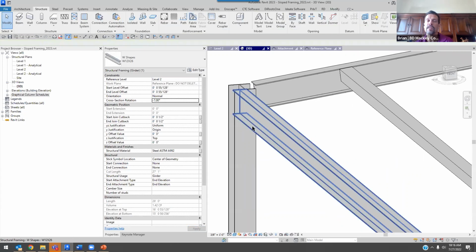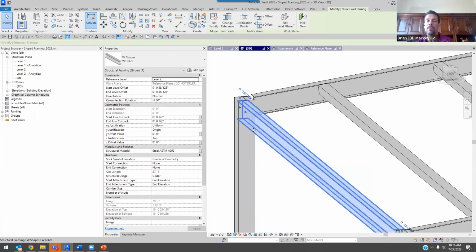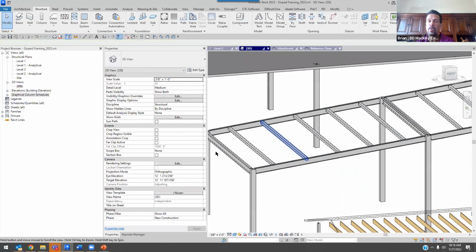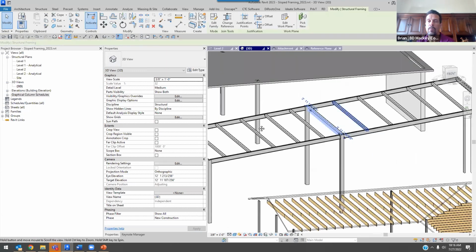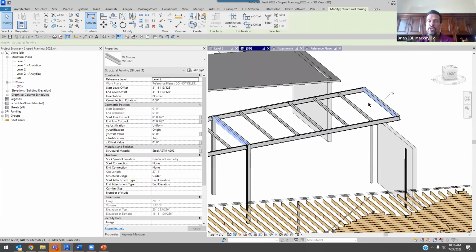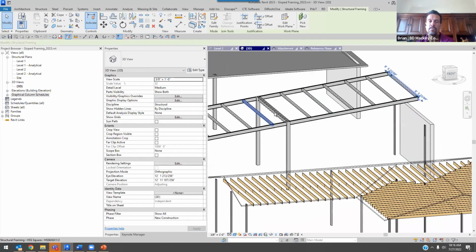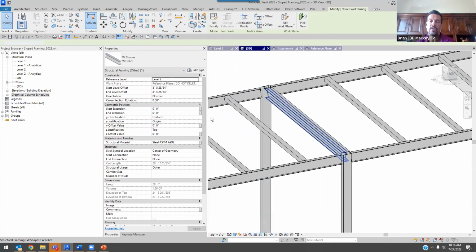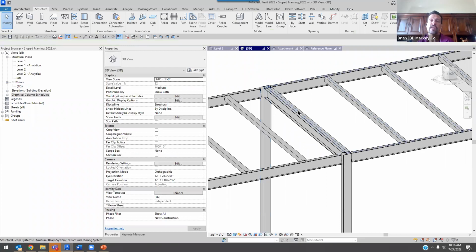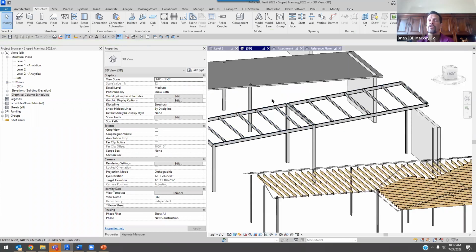So when we start setting that up, if you did want your beams plumb, you're going to have to come through and determine, oh, well, I needed that one plumb, maybe I needed that one plumb and that one plumb. So I should be grabbing, not what I meant to do, this one here and this one here, and I'll grab those and say, hey, you know what? All of those needed to be that -7 degree rotation. Okay, so you do have that. That can be an advantage or a disadvantage, just understanding that's what it needs to do.